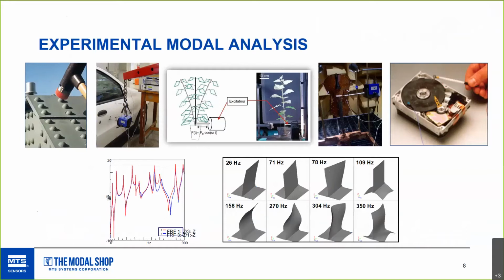So, we'll start off with what is modal analysis. We aren't going to go into a deep dive on what it is, but at its core, it's just the study of how a structure responds while being excited. So we're looking for natural frequencies, mode shapes, and damping. Then we're typically going to take this information and use it to validate a finite element model, so that you're able to make some choices in your conceptual design phase versus waiting till the end product to find out there may be an issue.